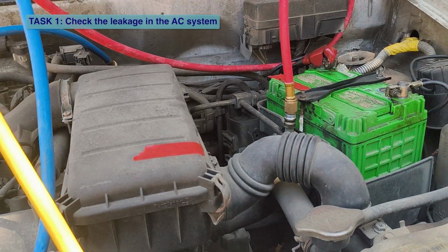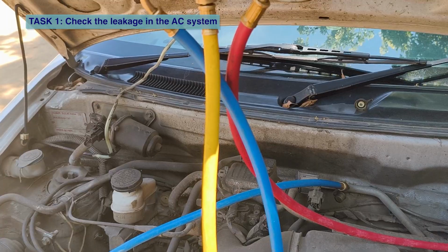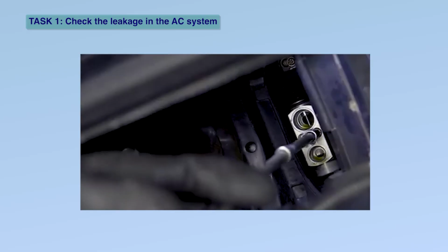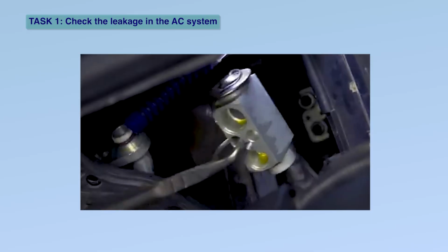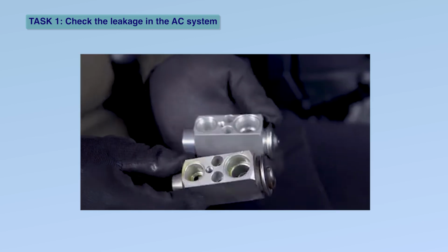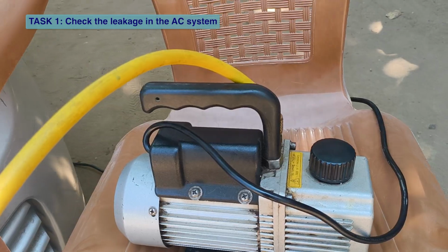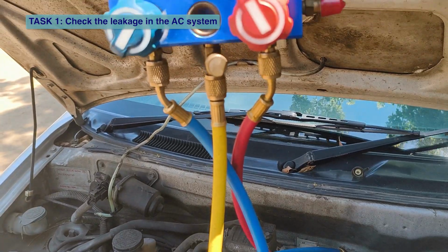Use dry nitrogen to pressurize the system and check for leaks when the refrigerant is removed. Inspect the expansion valve for leaks or malfunction as it regulates refrigerant flow. Make ready for vacuum test on the system to check for leaks by monitoring how long it holds vacuum.